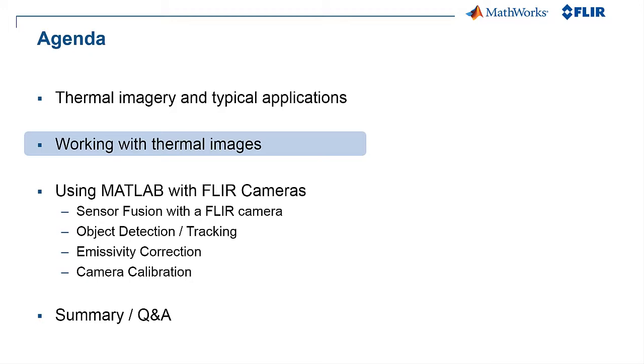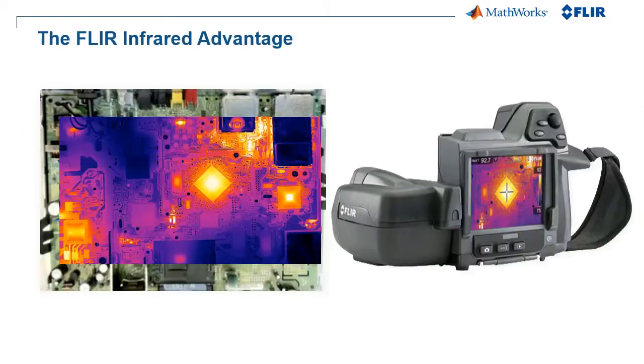Oh, that's a great question. There's primarily two ways to do the thermal analysis with the cameras. One way is to do it right on the camera itself. We have some camera systems that almost look like camcorders. And they behave very similarly, except inside of the camera there's a thermal sensor versus a visible CCD. So with these camcorder-style infrared cameras, we can capture still images, we can capture movie files, and we can do thermal analysis directly on the camera. We can apply spot tools or area tools and extract temperature information right on the camera.